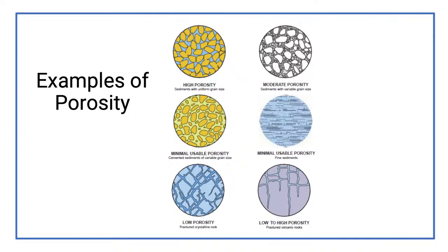So if you just have a fracture that's got water in it, that's not as good as a whole series of interconnected fractures where the groundwater can move to the well and you can recharge that water. So bedrock will vary from low porosity to high porosity, and we'll talk a little bit about the concept of secondary porosity here, because most bedrock in and of itself, unless it's fractured, has low porosity. And to get porosity, you've got to break it up, and that's called secondary porosity. We'll talk about that in just a minute.